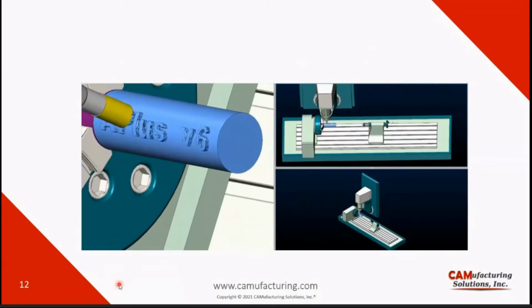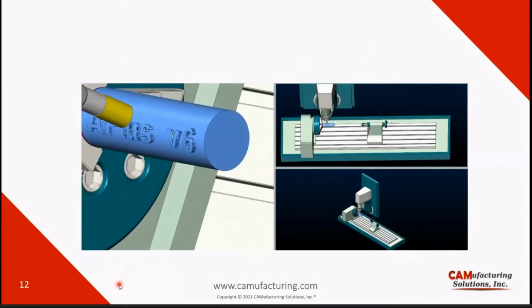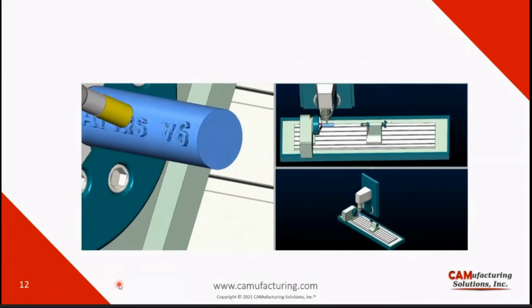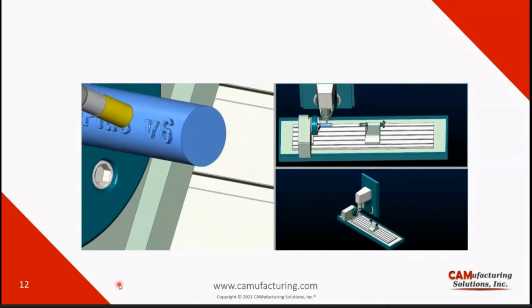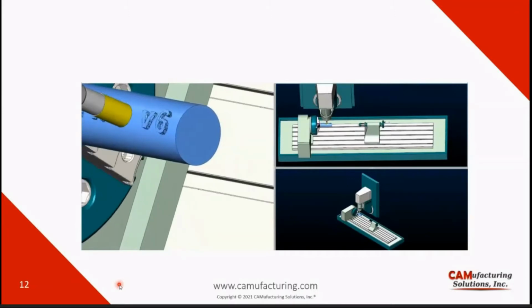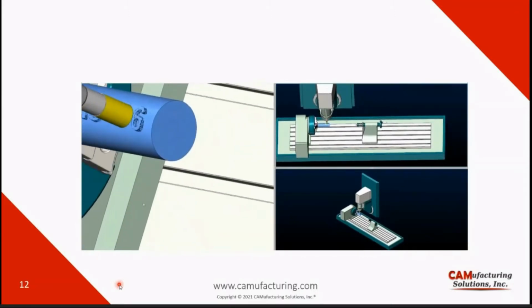It can be used as a stock model for the final machining, which is used in this example. So as you can see, instead of doing a lot of machining, wasting a lot of material, with just one directed energy deposition toolpath and one very simple and fast surface finish, you will get your roll direct.